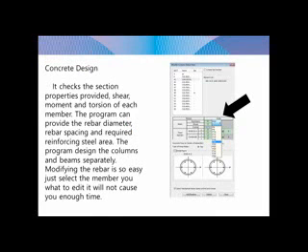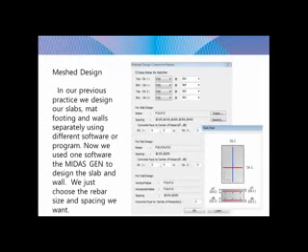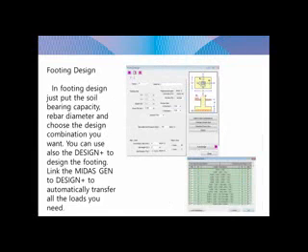Same with the mesh design. In our previous practice, we designed our slabs, mats, footing, and walls separately using different software or programs. Now we use only one software, the MIDAS Gen, to design the slab and wall. We just choose the rebar size and spacing we want. Footing design. In footing design, just put the bearing capacity, rebar diameter, and choose the design combination you want.